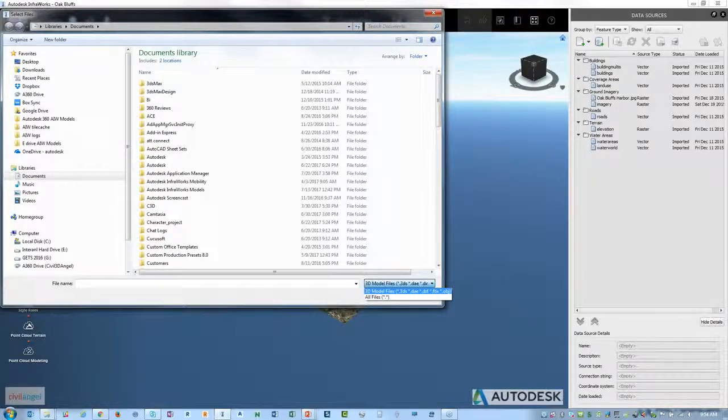The other thing I've done is I remember bringing in a certain FBX, maybe it was a Lamborghini, and the Lamborghini was red, but I wanted a blue Lamborghini and a black Lamborghini and a gold Lamborghini. So I brought them into Navisworks, applied different materials to them there, and then exported out new FBXs. When you're dealing with a collection, you have lots of tools at your disposal that allow you to create very custom objects very quickly, very easily.